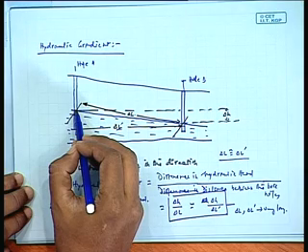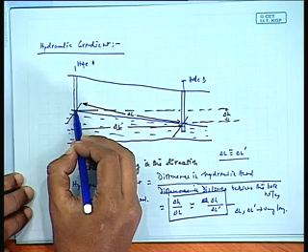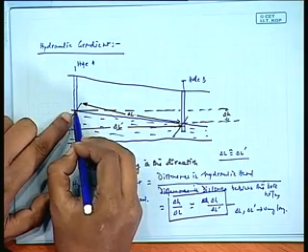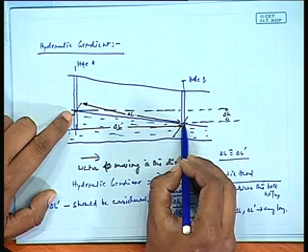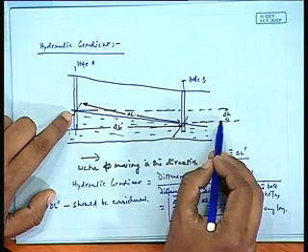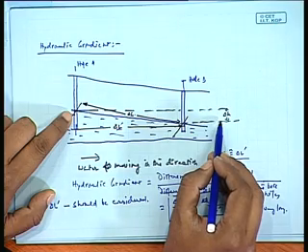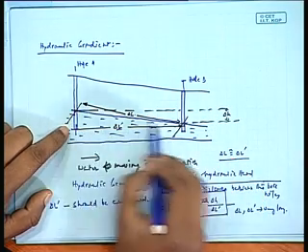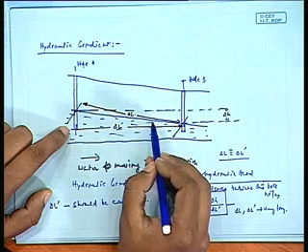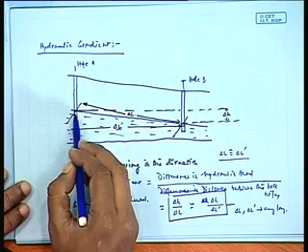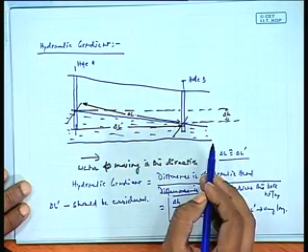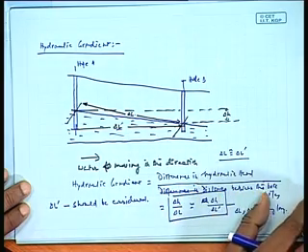In the boreholes, the piezometric water head is calculated. It's nothing but when you strike the water level here and the water level here. The difference in these two levels should essentially give you del H, isn't it? This should provide you del H. So having found del H, and if we know the distance between them, you can find out the hydraulic gradient. The basic principle is that water from a high head would travel towards the water at low head, right?